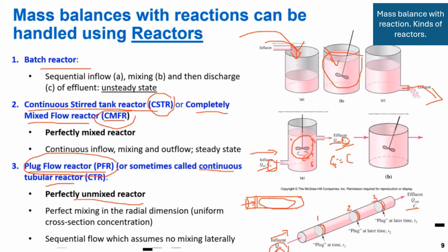It's different. All right? The assumption here, this part, the small plug, the small volume here, we are saying that there is no radial, no axial mixing. This part here is not mixing with the other neighboring part. They only mix together radially. This part here, they mix together at only this stage, only this part, radially. All right? So this is the mixing only at that specific point.